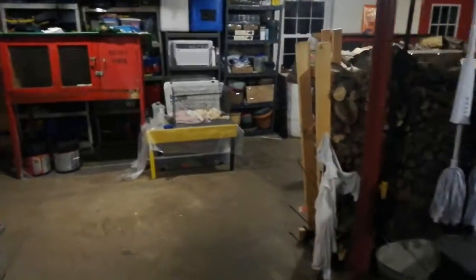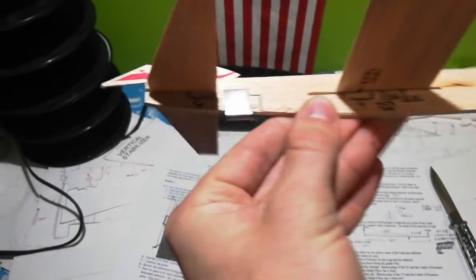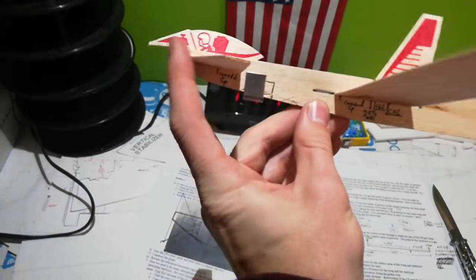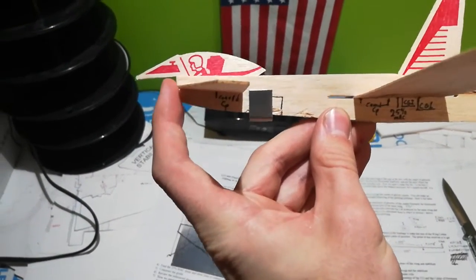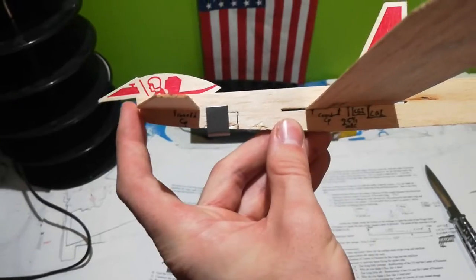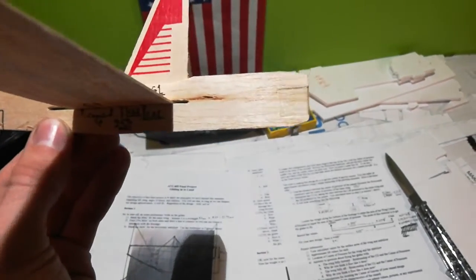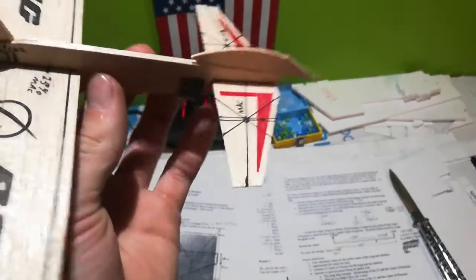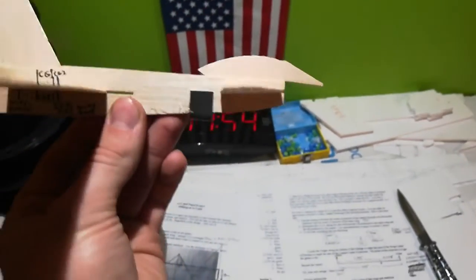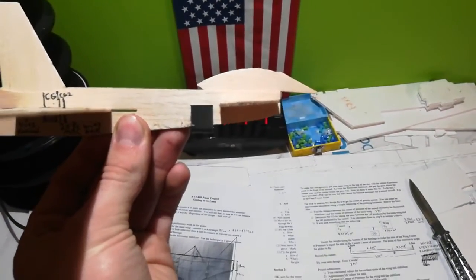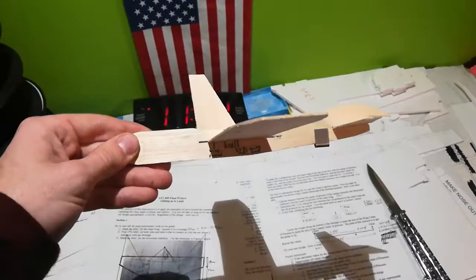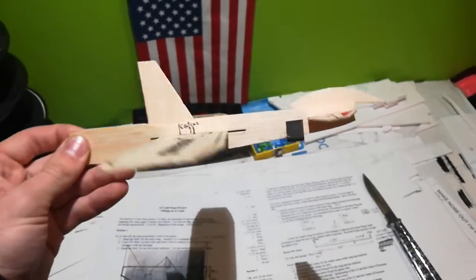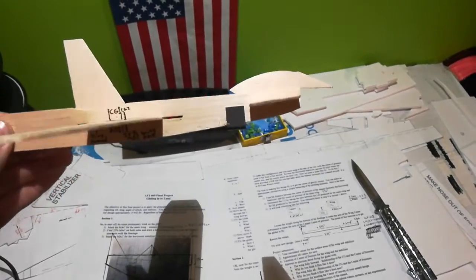It does indeed glide. So as you can see, you need the weight pretty far forwards now to counteract the positive lift here by the canard, as opposed to before, you needed it very far at the front to oppose the downward lift of the horizontal stabilizer, because you can see it is at a negative pitch relative to the main wing. That is why normally aircraft can fly faster and be more efficient when they are slightly tail heavy,